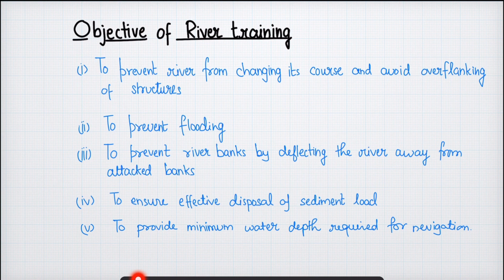In the previous lectures, we have discussed that as an irrigation engineer, you do not want too much silting or too much scouring, but yes, there will be certain silting and scouring, no matter how efficiently you design a channel. If you go into too much quality control, there will be too much cost incurred that may surpass the benefit of the irrigation structure that you are going to get, right? So you allow a certain amount of silting and scouring, but that should be under your control.